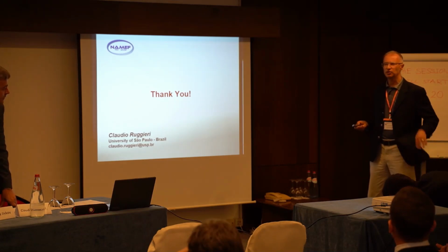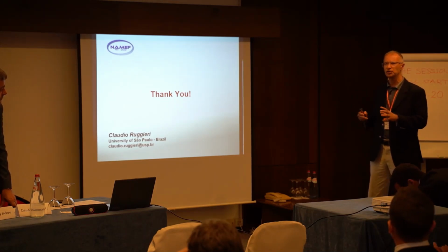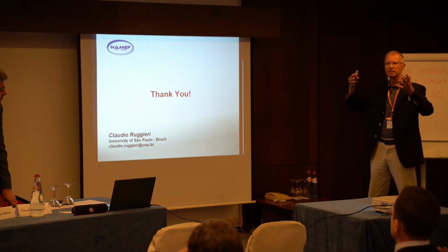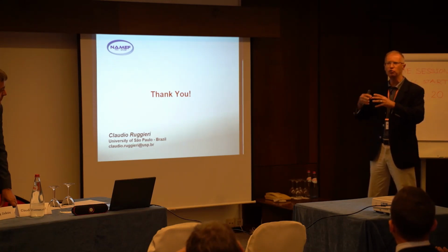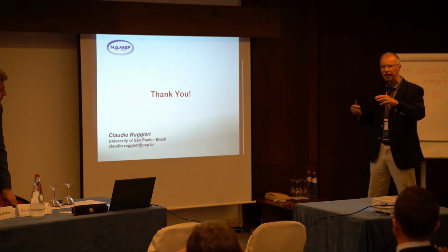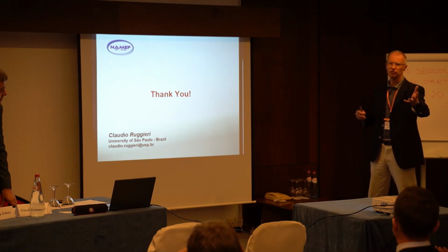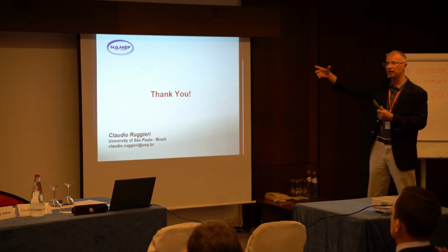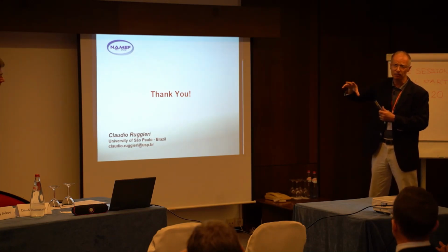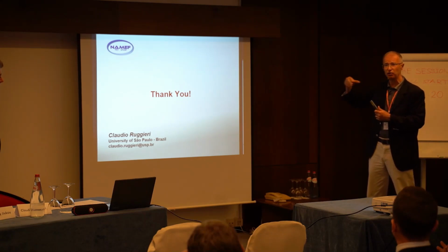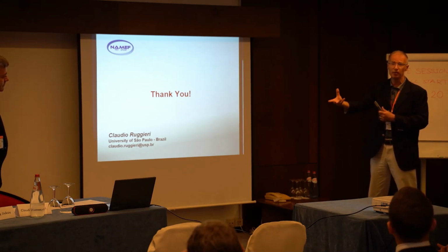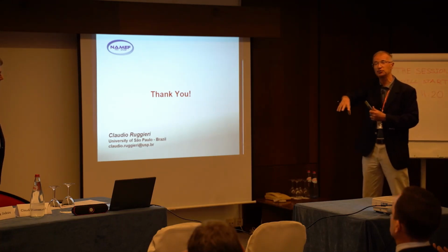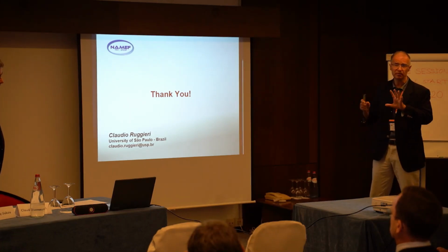No, they are not equivalent, because the standard Beremin model does not consider any plastic strain effects. Perhaps the form is the same. The closed form is very simple. That's why, for example, we can use the same code. You just have to plug in the plastic strain effects. You don't need much modification. That's the main advantage of this. It has some limitations, but the main advantage is that you can use the same framework as the Beremin model. You just have to plug in the evolution of plastic strain in each element. They are very simple.